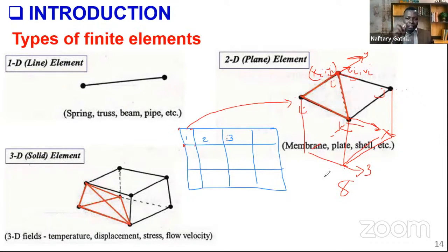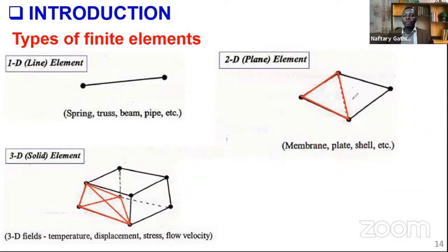So you can imagine one element has 24 degrees of freedom, telling you how many unknowns our equation will have: 24. So the stiffness matrix will be 24 by 24 if we disregard the rotation. That's why I'm saying the computation power of computers now comes into play. I don't want to overwhelm you so much because it's just an introduction and overview, but I wanted you to appreciate, as we move from 1D to 2D, why we really need to use computers, why you really need to install Abaqus and do this analysis, okay?